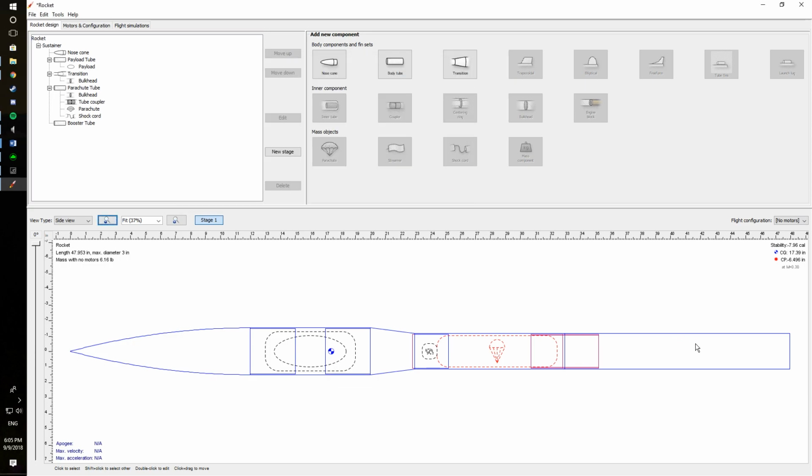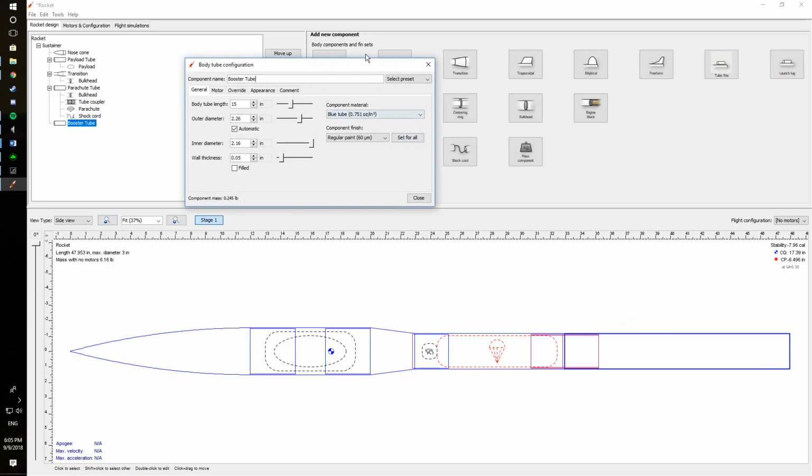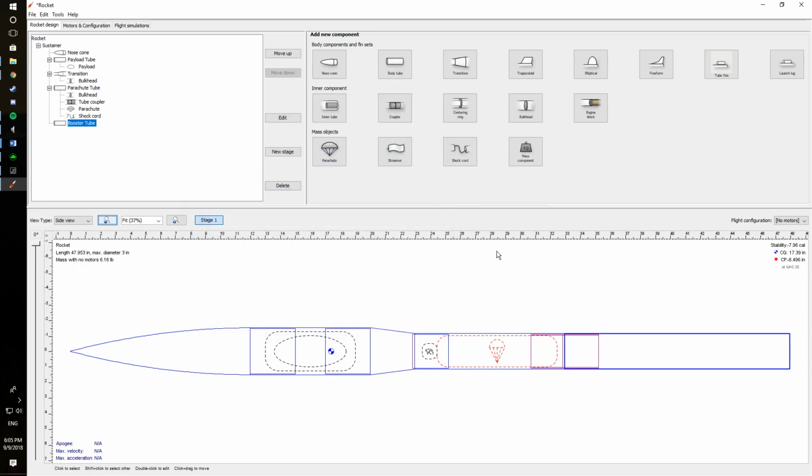The last thing you should notice, now that we have a general rocket that is nicely filled, is that our stability is completely garbage. Stability is essentially the measure of the distance between the center of gravity and center of pressure, and you can see the center of pressure is nowhere on screen, so our rocket would just tumble indefinitely, be a hazard to everyone, so we need to add fins to balance this. Adding fins is as easy as everything else.